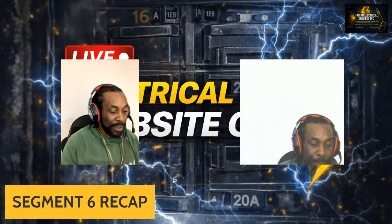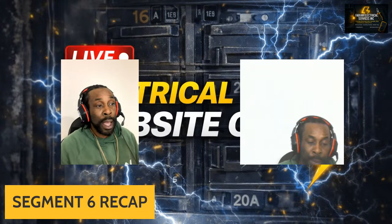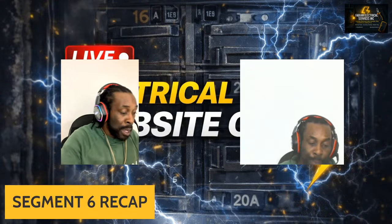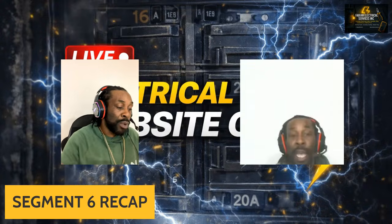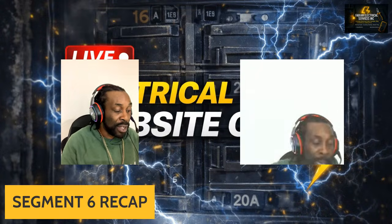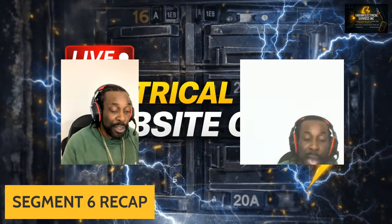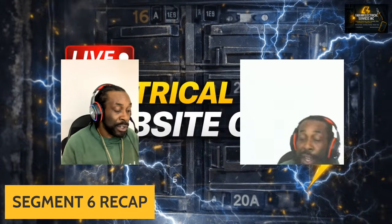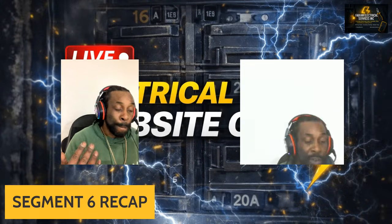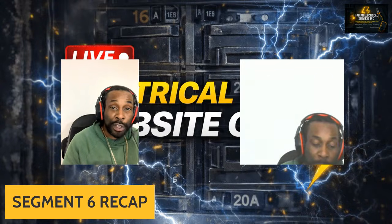This is basically a recap of the live stream tonight for all those who are tuned in. What we would have discussed, segment 1, would have been breaker basics. Breakers protect the conductor, not the device. 15 amp versus 20 amp circuits. So the 80% rule, continuous load.